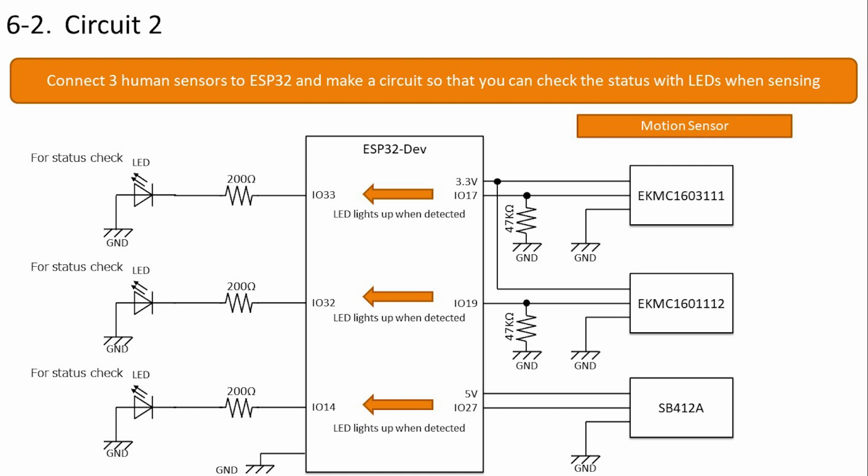As a reference, I checked whether pull down can also be done programmatically. It compiles and writes fine, but detection didn't work. I was able to program pull up, but for pull down, I may have to connect a resistor.